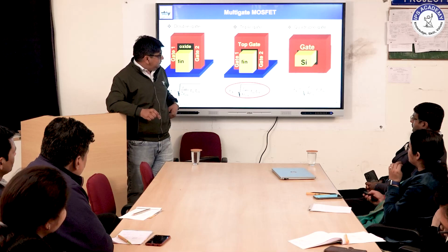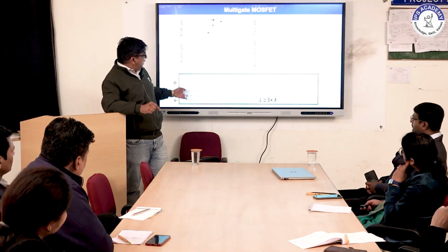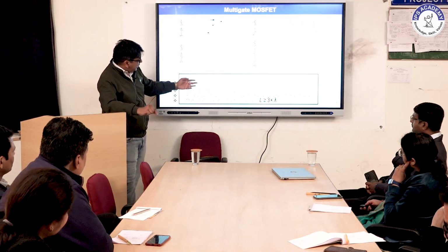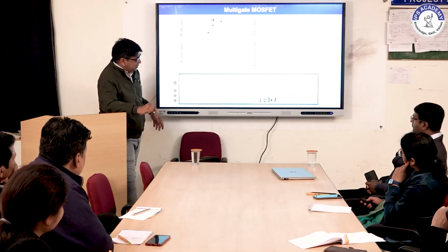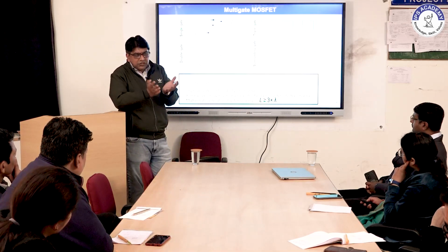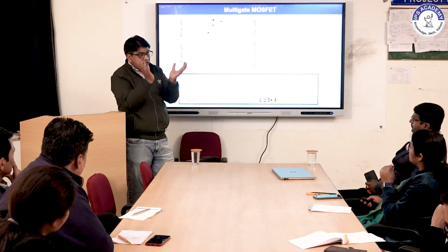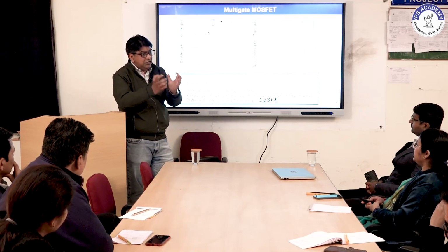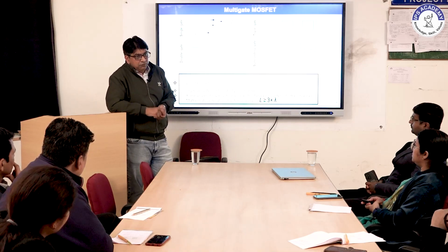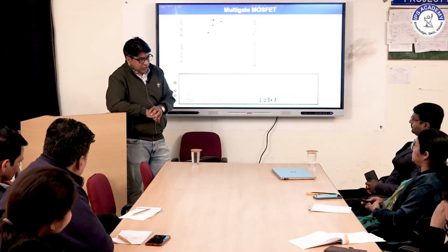Come to the next slide. These are the advantages. Volume inversion: volume inversion means, because the entire side gate is there, the channel will deplete entirely. So we can use the entire channel for the conduction aspect.